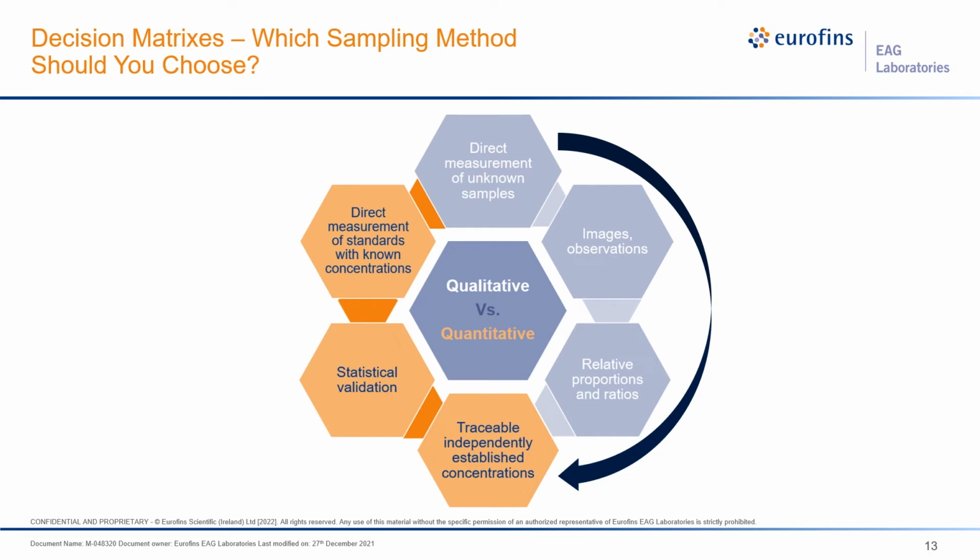So it's only through analysis of reference standards with similar compositions to the sample, with accurately known concentrations of some or all of the elements of interest, and typically complex data reduction methods, that these qualitative data can be converted into a quantitative concentration. Quantification requires the systematic testing and development of standard operating procedures, which is a time-consuming process, requiring round-robin testing at independent labs and/or publication of methods standards with bodies such as ASTM. For many advanced materials with unique or unusual compositions, there simply are no reference materials available.